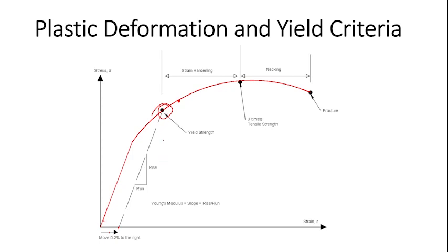Due to that, more number of dislocation will be present, that will start interacting with each other. So next time when you will start to deform this material, you have to put more strength in order to deform that material. So this effect is called strain hardening. The more you strain something, the more hardened or stronger the material will get. That is what is called strain hardening.